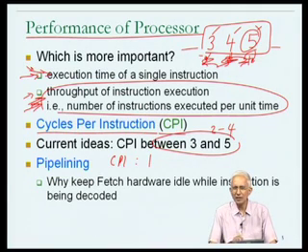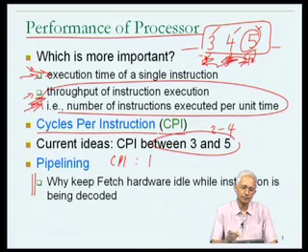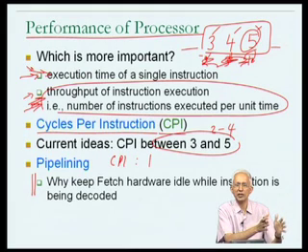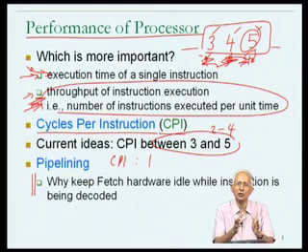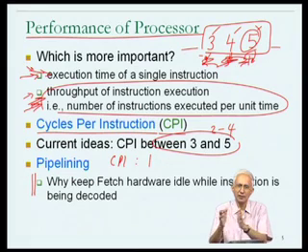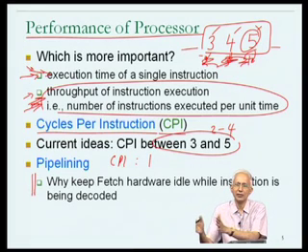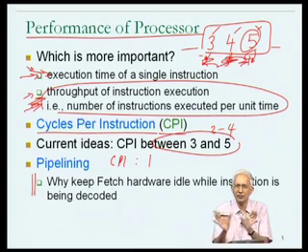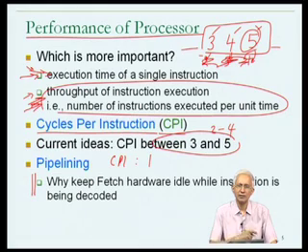Now, the basis of the idea of pipelining, from the context of the hardware that we have seen, is to try to get an answer to this question. In building the hardware, we had the hardware to fetch an instruction and increment the program counter, the hardware to decode an instruction and access the operands, then the hardware to execute the ALU, etc., and the hardware related to the access to memory, if it is a load or store, etc. And then we just put these pieces of hardware one after the other and expected that it would be used to execute instructions.